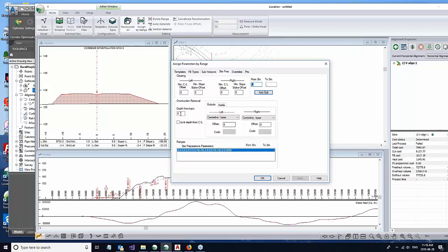Now I want to do some stripping. So I'm going to strip 0.3 meters. Quick question, Craig. Quick question, okay. Is the Civil 3D horizontal spiral data recognized by Optimal? Yes, short answer is yes. We do recognize the horizontal spirals. That being said, there may be some exotic spirals that we don't handle, but I think we handle most nuts and bolts spiral curves.